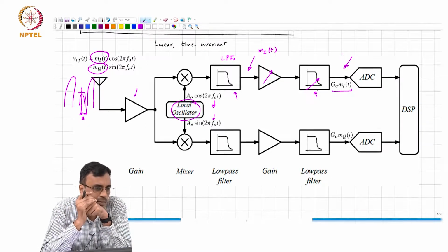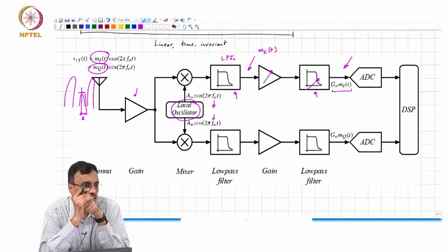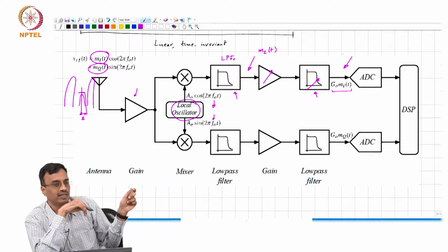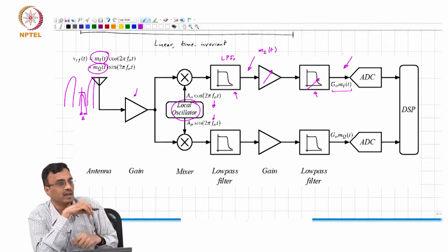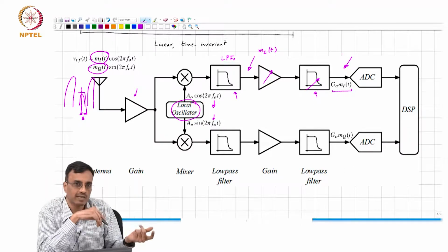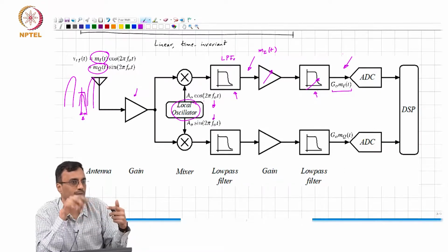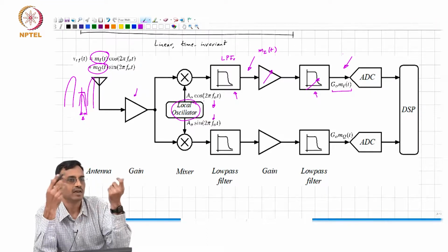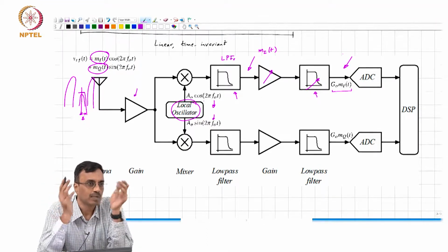Basically, as the frequency of the band pass filter becomes higher, if you want to receive a certain signal bandwidth at a much higher frequency, you have a double whammy. Not only is the center frequency higher, so any band pass filter you make becomes more difficult to do, the Q also becomes higher, because center frequency is higher and bandwidth remains the same.